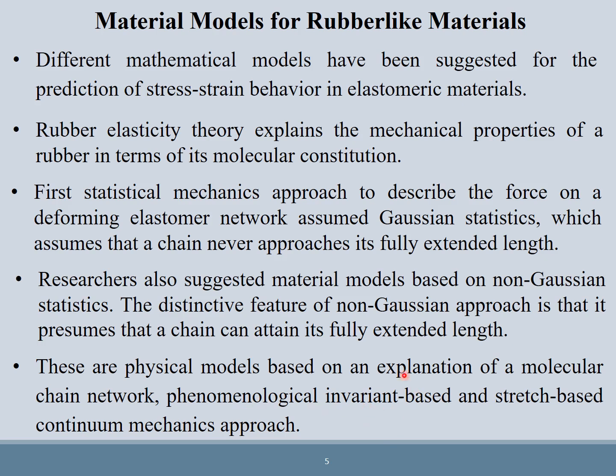So based on that, in terms of invariants, we have material models. In that material model, we have invariants as a variable. It means I1, I2, I3 are present in that equation, and then stretch based. And what is stretch? We have generally studied the strain. If L_f upon L_0 is a stretch, so a stretch based continuum mechanics approach is also present there.